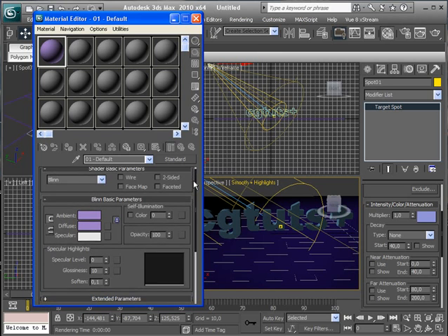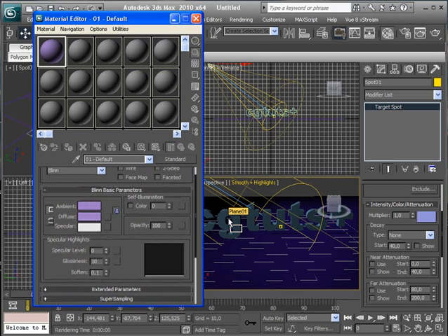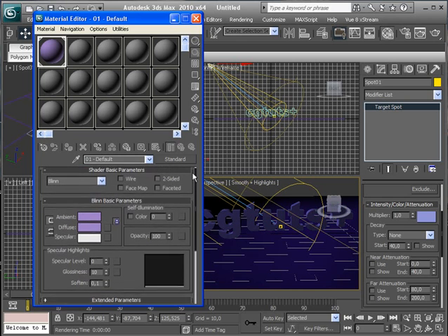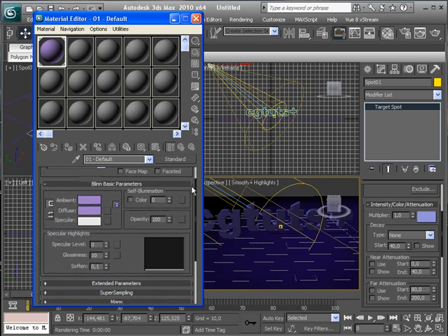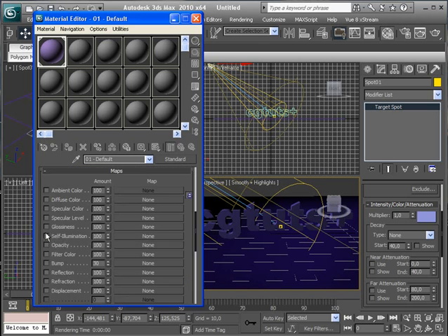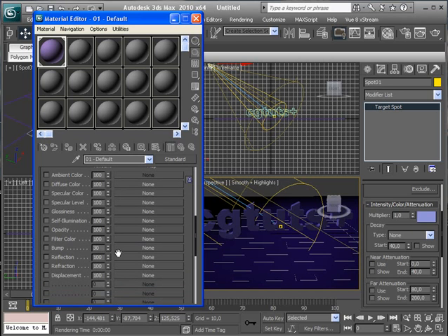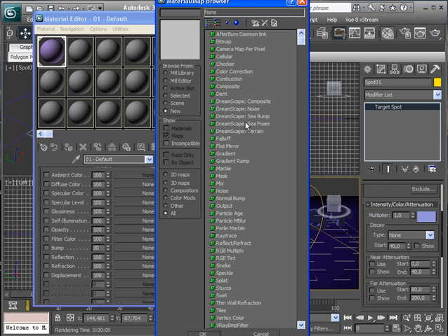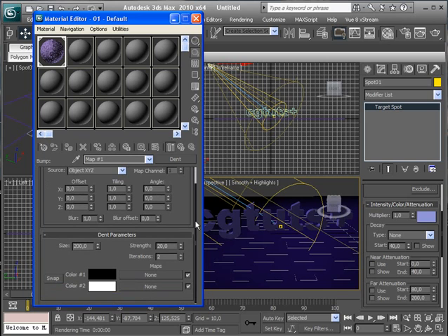That's it. After that, let's apply it first to our text. Then we need to create the holes in the text. So I'm gonna use a bump map. Just click on the bump map, and we're gonna add a dent to it. I'm gonna add dent. So for the size, I'm gonna input 22. For the strength, 10, and we're gonna input 3 iterations.